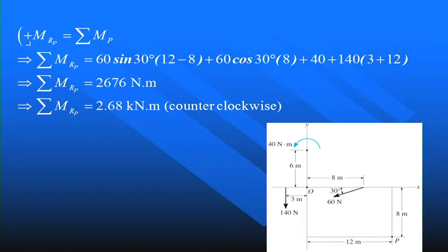That means we first resolve the force into x component and y component, then calculate the moment of these two components about point P. This makes the calculation easier.